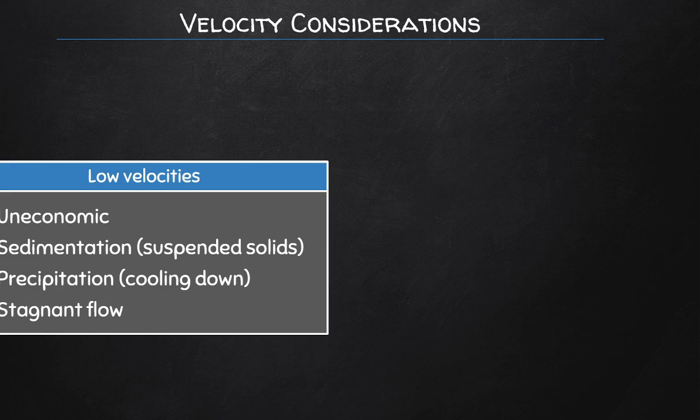Now, during my time in industry, this was a serious issue for one of our bleaching towers that I was working on at the time, where several thermocouples were reading lower than expected temperatures due to stagnation, where the flow had stopped. It's like a massive reactor, 6 meters in diameter. The flow was just not flowing. It was flowing laminar in the center and not flowing at all on the side.